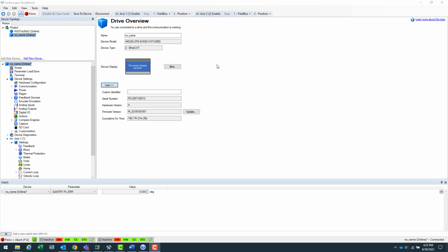So I'm going to go over the basics of gantry mode while I'm in the Kollmorgen Workbench application. We do have Workbench integrated into the KAS IDE software, but a few of these parameters aren't shown. For instance, you can't change the command source inside the KAS IDE, so I'm going to demonstrate it connected directly to the AKD2G drive's service port and using the separate Kollmorgen Workbench software.